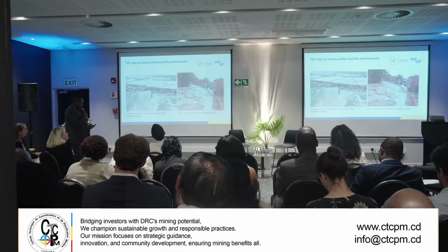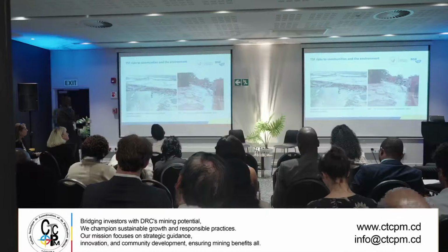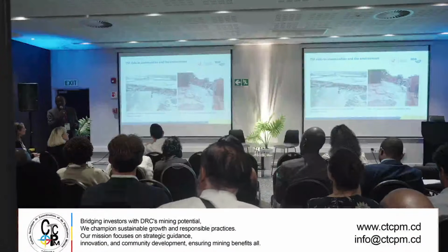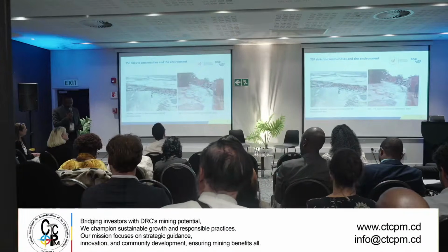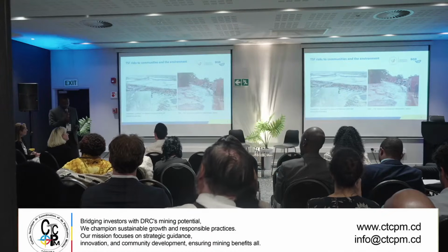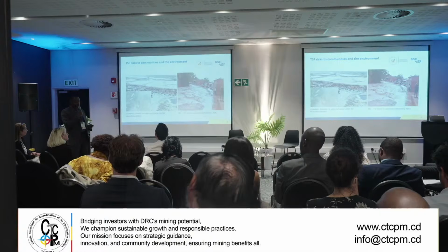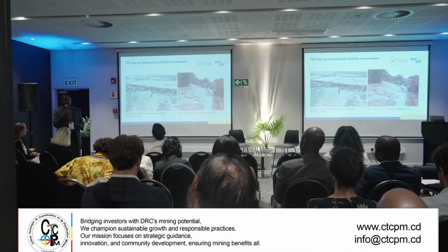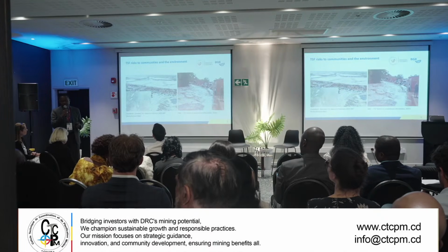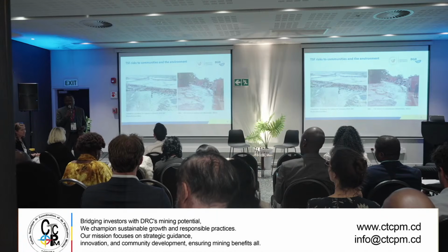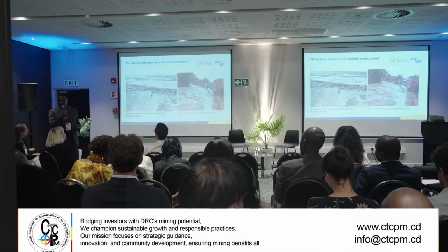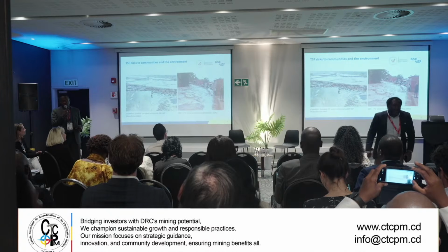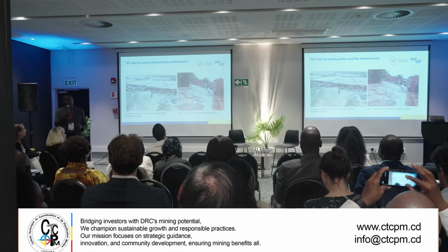Either you have a tailing storage facility, where we need to monitor the stability, the membranes, and how they are in the long term, or you have a waste rock dump, the WRD, as I've seen somewhere. You need to be monitoring those things. And the problem in the DRC is that we know what is currently in operation, but we have mostly forgotten what was operated years ago. And this study is good because we've done it with the remote sensing method.